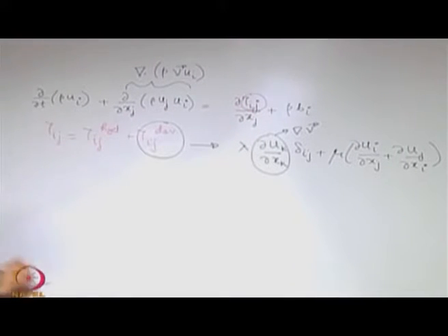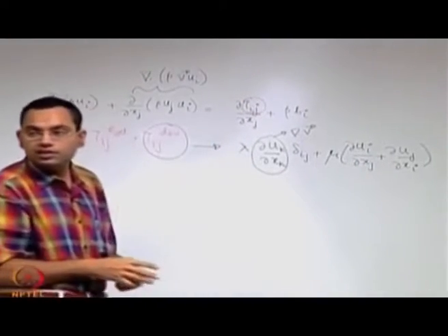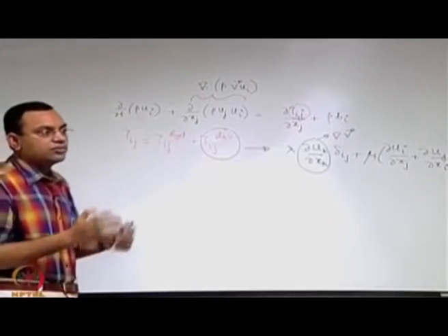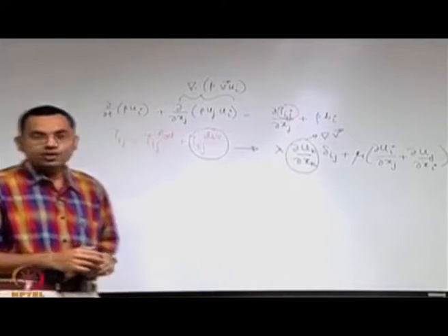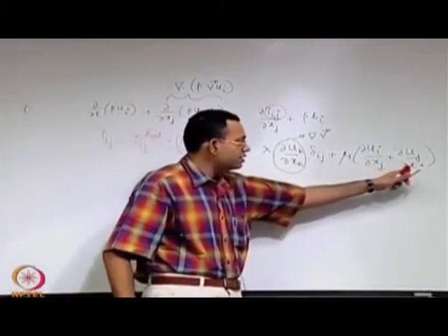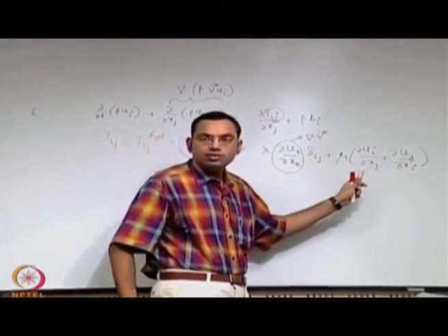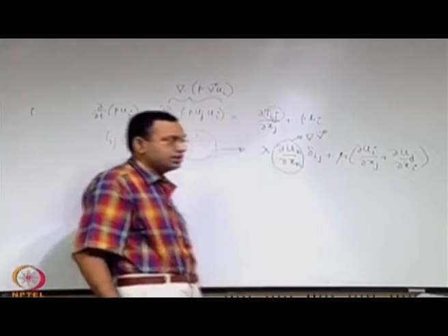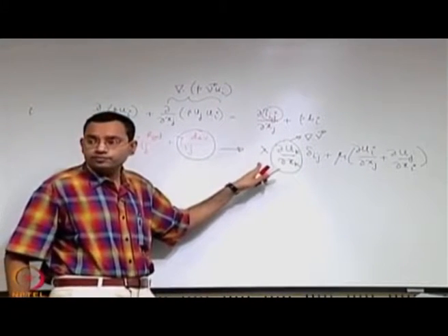And of the angular deformation, we have seen that it is the shear deformation that matters for the stress, because the rotational component is an effect that does not give rise to any viscous stress. So only the symmetric part of the deformation is going to give rise to the viscous stresses. What are the assumptions under which this is valid?